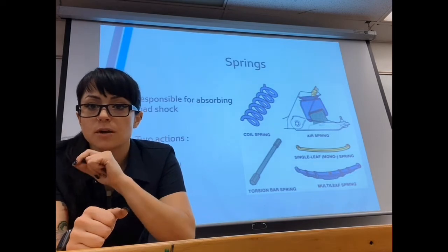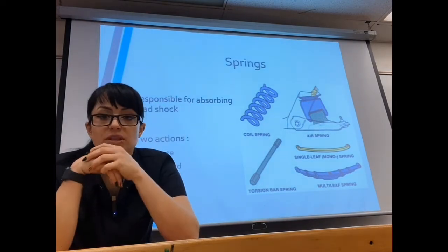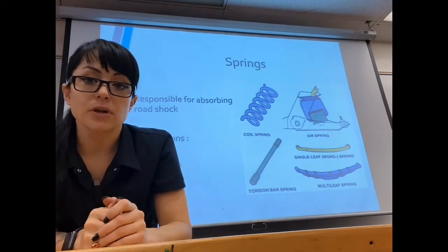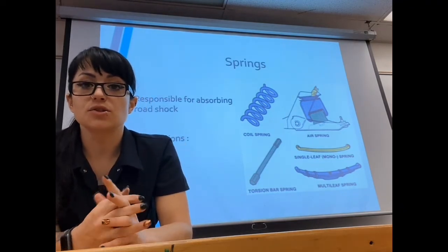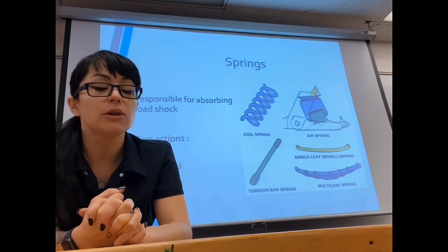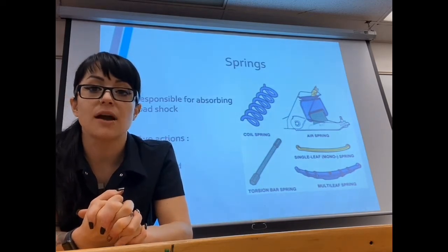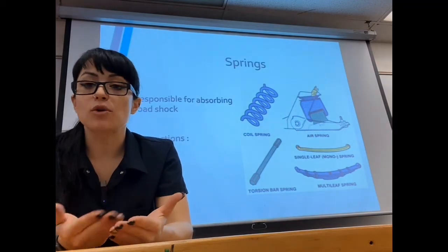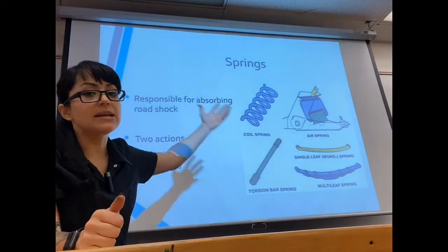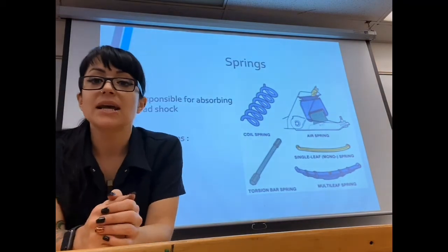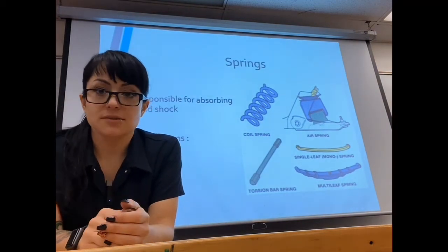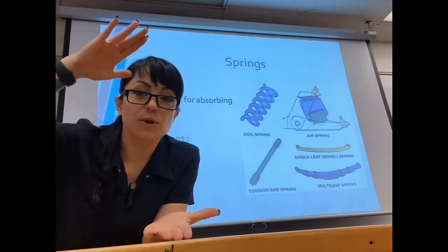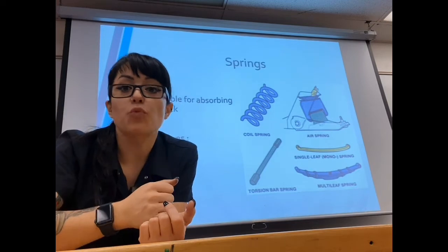We'll talk more about shock absorbers because they work in conjunction with springs to make sure that happens as well. But springs are also going to be one of the main contributing factors to your ride height. Not the only one, but one of the main contributors to what's going to determine your ride height. Now your springs, no matter what kind of spring, because there are so many different designs, we'll talk about that in a minute, have two actions. They are either in jounce, which you might know as compression, so that spring compresses, and then we've got rebound.